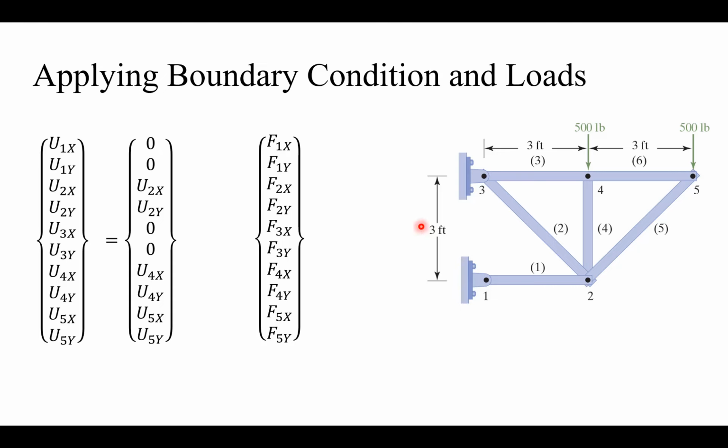Same thing for forces. For forces, we have external forces and also reaction forces. Now I'm going to write all of them together, but later on you will see I will separate external forces from reaction forces. They need to be treated differently in our analysis, and that's a very important step. Well, for now, let's see. Whenever we have information about the displacement, whenever we say the displacement here is 0, that means that we have a reaction force.